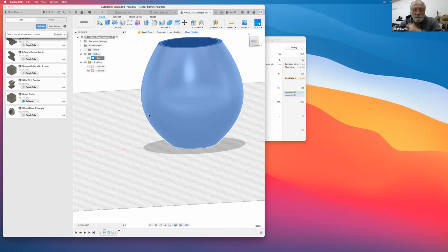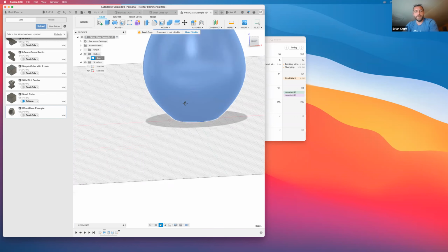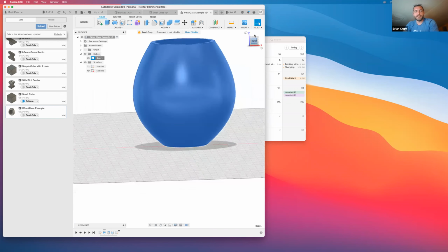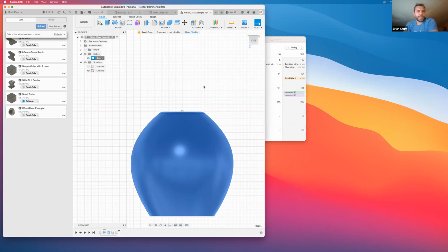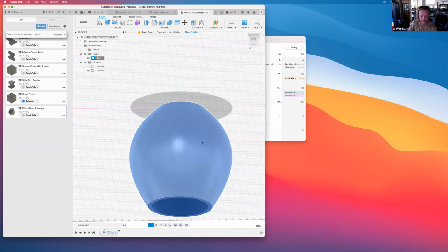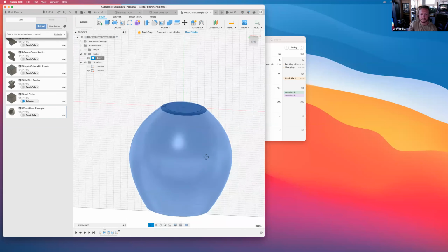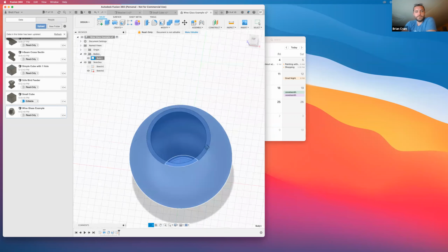Yeah. And in this example, do you need the solid base? If we were just to flip this 180 degrees, so the print surface is the rim and the solid base is at the top, and if you had a gentler curve at the bottom and a more extreme one at the top, oh, but then you have the problem of closing it solid. So from the perspective that you're discussing the outside angle, yes, I would say that's absolutely correct. But you are right that now we have to put support structure on the inside of this thing. So there's that to consider. But yes, you're right in terms of the curve.